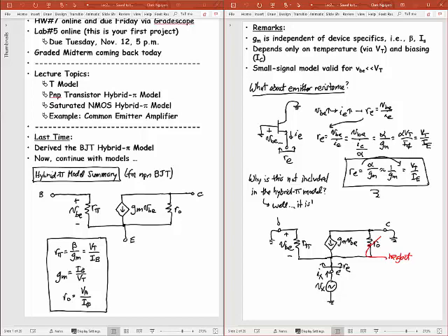If I go ahead and do that, I can use some of the derivations we already have. So I know VBE is the voltage that I might drive this with. I know that this current here is I sub E, but I also know from the previous discussion that I sub E is just equal to the collector current I sub C divided by alpha. Remember, where alpha is equal to what? Who knows what alpha is equal to?